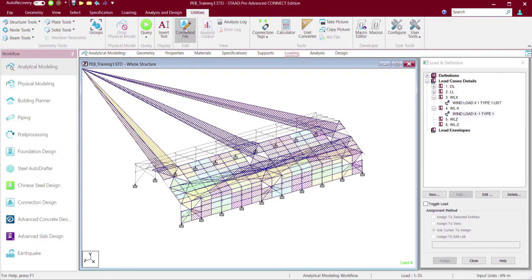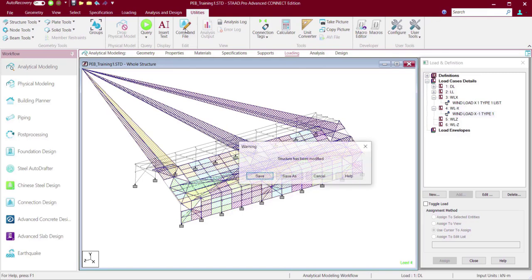Just reverse the direction. But the moment you reverse the direction, it looks very scrambled because this time it is hitting on the opposite side, and as mentioned earlier, it is considering all those irregular geometries, including those bracings and all, and that's why the loading looks very scrambled. So the way out here is to properly organize them with the group name.